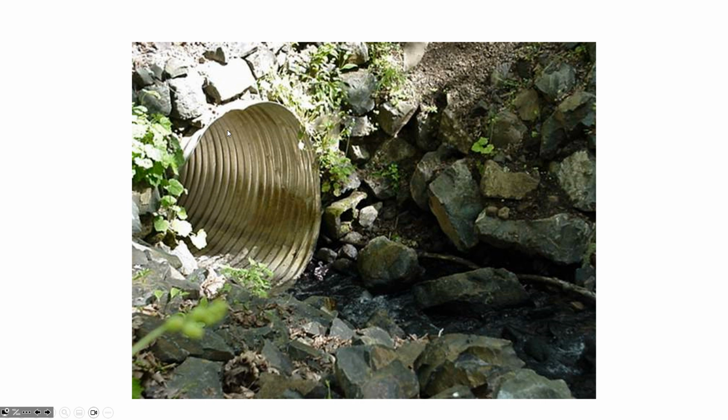The corrugations provide quite a lot of strength, and it's not as flexible as it would be if it was uncorrugated. But with enough load, on a circular pipe, you'd want to pack quite a lot of soil under the haunches of that pipe, because when a heavy load is applied, it begins to be a little bit deformed this way, and it compresses the soil that was underneath in that area, and as the soil compresses, obviously it's going to be pushing back.